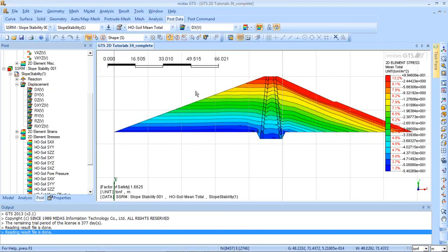This type of coupled analysis, MIDAS GTS also supports, like consolidation and stability. So I would also be helping you with the same, so you can see what the various coupled analyses are which could be done in MIDAS GTS. For now I have chosen seepage slope stability analysis as per the model you sent. I think most of the projects which you do are basically focused on seepage and slope stability, so I have chosen this particular model for your requirement. In between, if you have any queries, please write them in the question box so I can answer them and I can proceed to the last model,